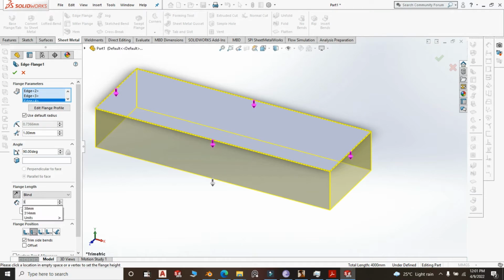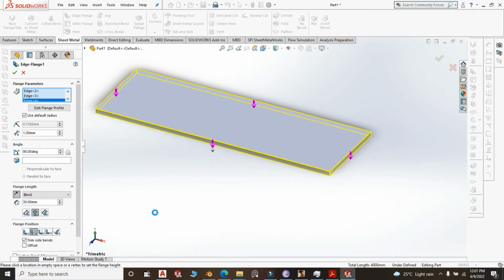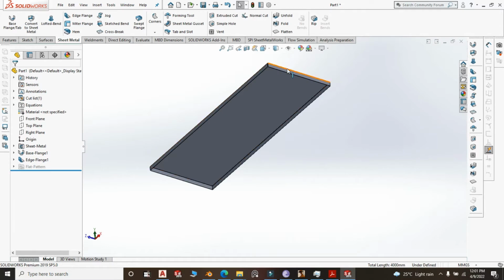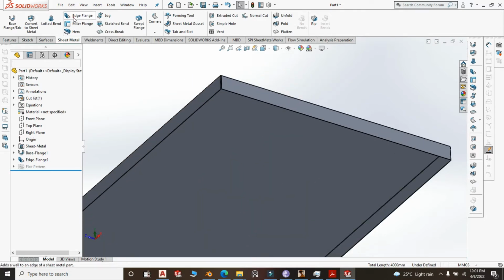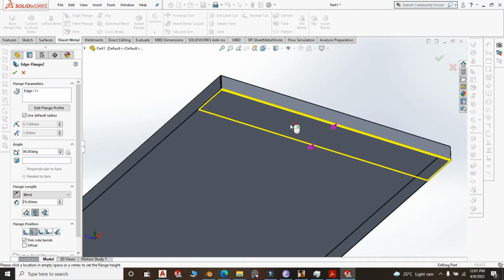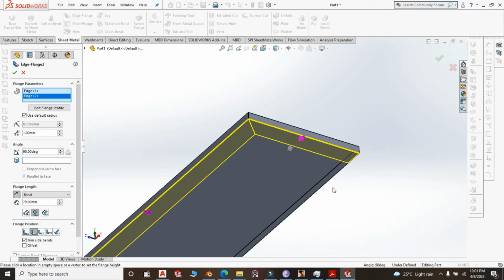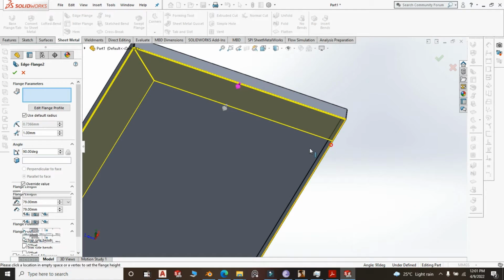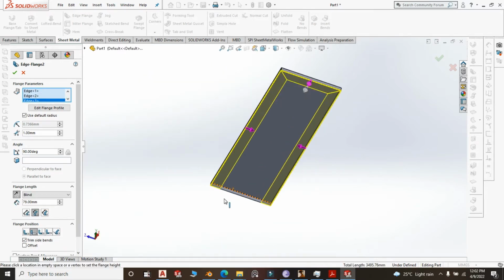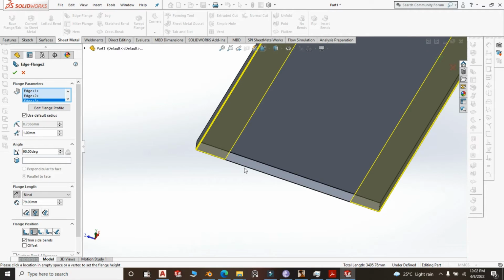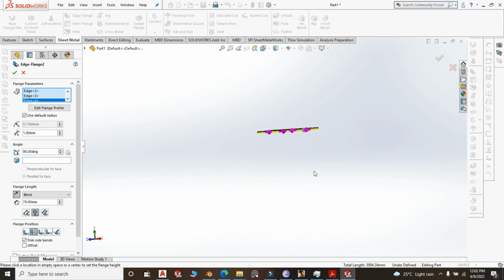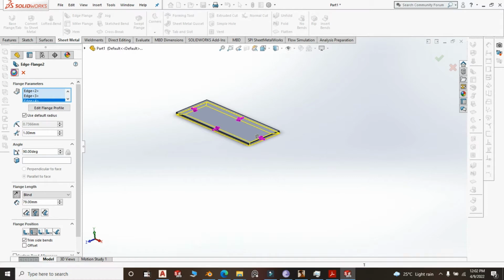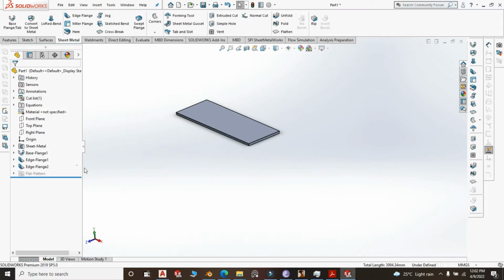Like we mentioned, that bend is 30 millimeter. Click OK. Then create a 15 millimeter bend edge flange here. Don't know why it is always 15, but 15 is very much suitable. And again, if I may mention, the size being 500, the reason is that you want to split your sheet into 2, so that from one sheet you get at least 2 shelves, right?